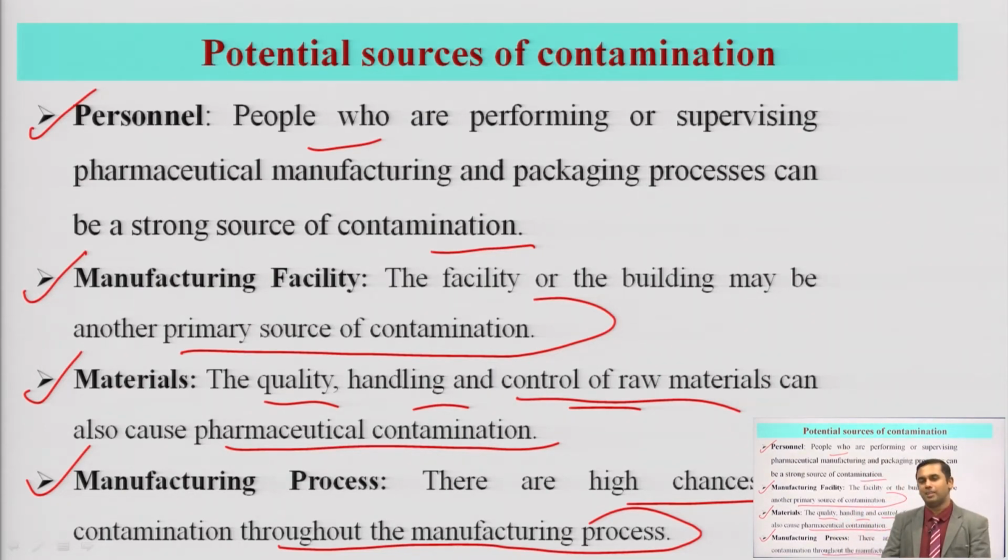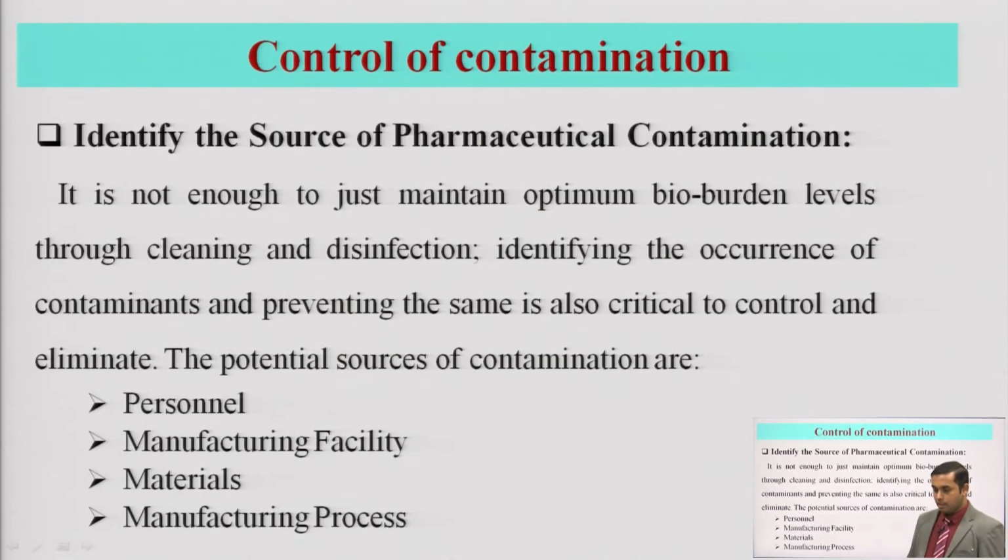He is carrying lots of bacteria, and he goes to the area where you have prepared this paste from starch. So bacteria will also come in, causing contamination. When it gets the starch, it will be able to multiply itself, and then your entire area, and the next time you use that area again, it will create a big issue. That is why it is manufacturing process related.